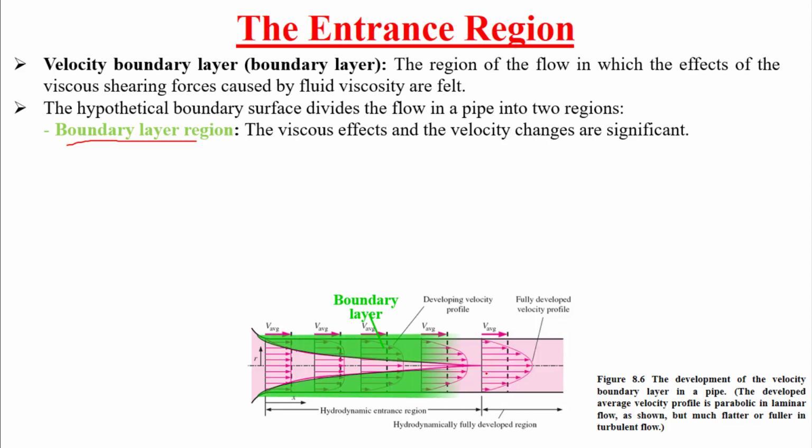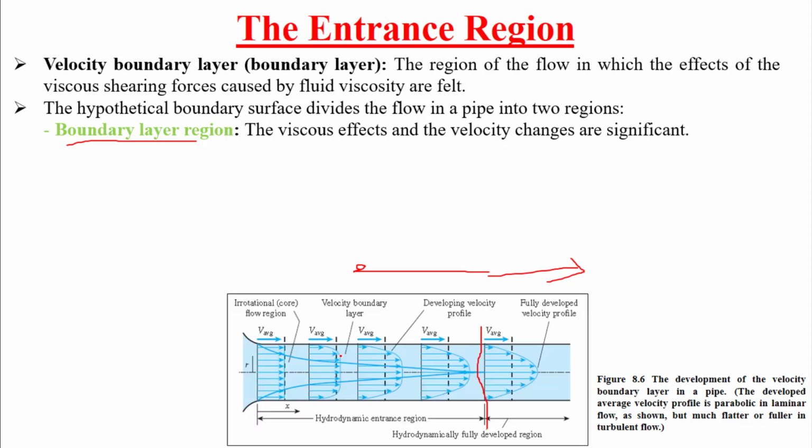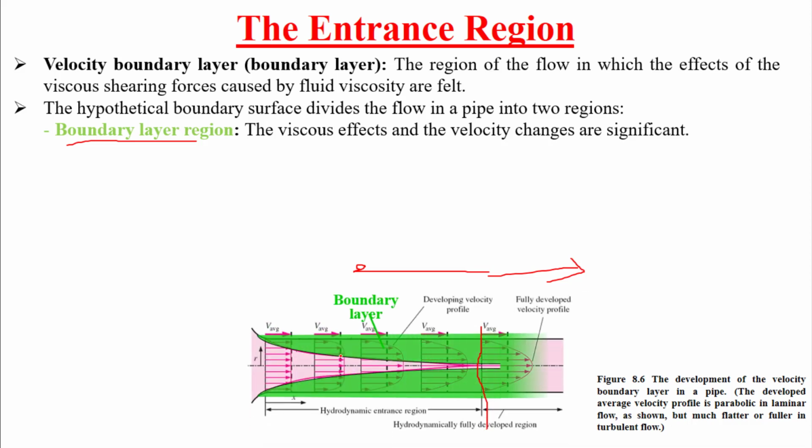It becomes united at this x. At this axis, it becomes one region when it enters the fully developed region. Before this, the flow is still developing, and the boundary layers are separated. See it again. They are separated until they reach the fully developed region.